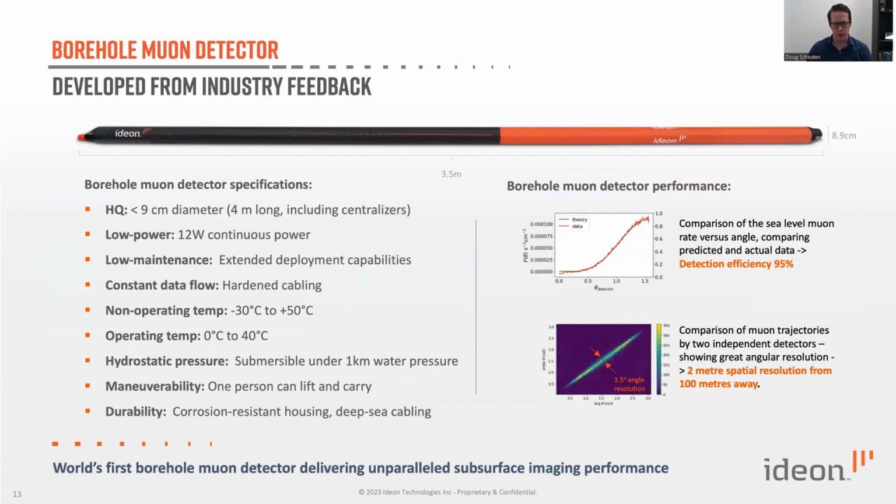So based on that successful outcome, we, of course, moved at haste to develop a borehole system. Again, a miniaturization of 50x, which was no small feat. But we developed an HQ-sized detector. So it's about 89 millimeters in diameter, 3.5 meters long, 4 meters long if we include centralizers. So roughly the length of a single drill rod, over which the borehole is assumed to be linear.